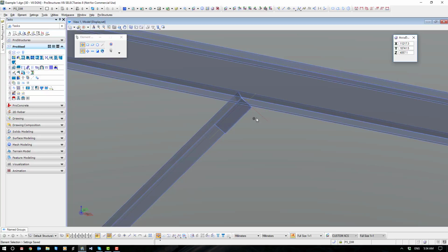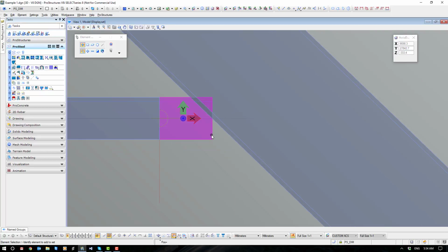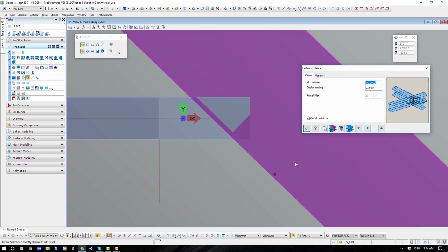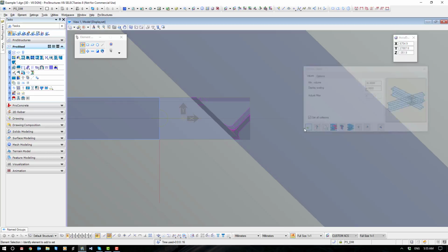So before we kick off on the cleat, let's shorten the cleat up, and I'll actually get the brace 20 mil off the steelwork first, so we know where to put our holes in our cleat while we're working on it. So I'm just going to shorten that cleat up, and then I'm going to go object view centered, don't align the view, and we're going to have a look at the side of the angle. So we'll get the angle set up first, that way we know where to put our holes and stuff. So we're going to drag this intentionally interfering into our beam. Then we're going to use collision detection and work out the interference between those two objects.